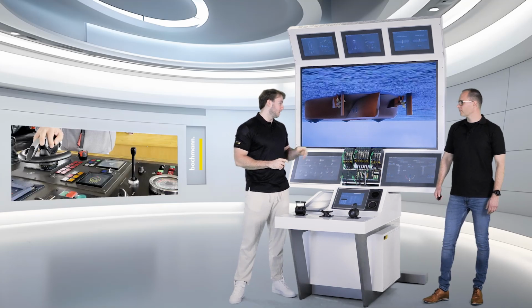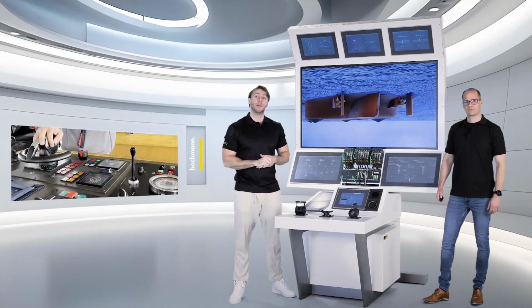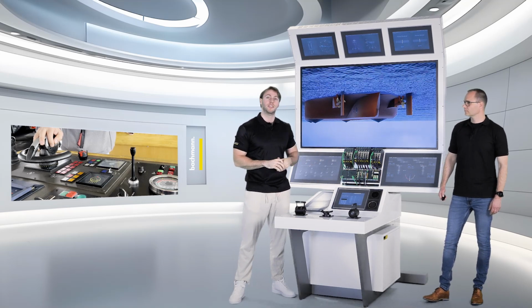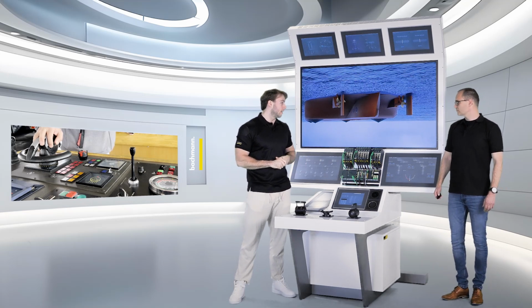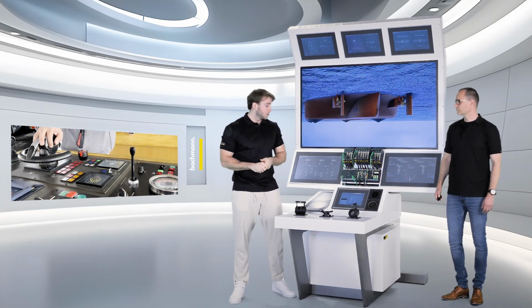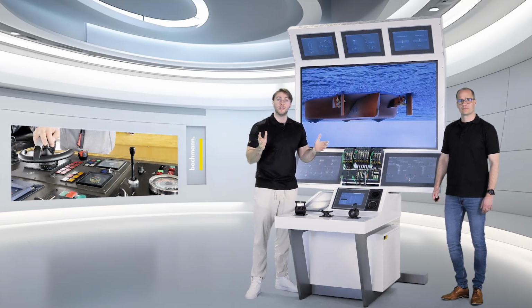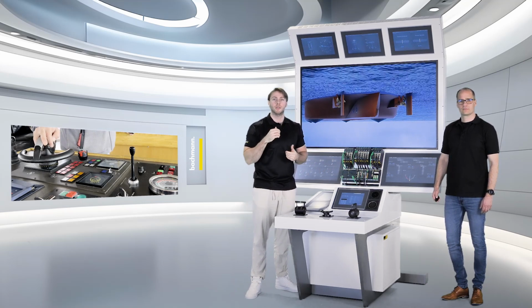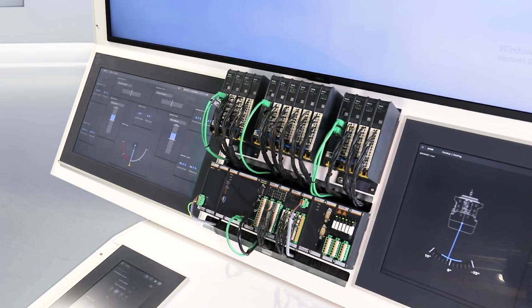So in this template we had a few objects in it, and also the brightness and the coloring of all the objects inside the project will change with a simple click of a button. Besides that, it also has some diagnostics to it. So first up, the M200 system. You have a full diagnosis on your HMI. You can click per card, per channel, and see what's wrong with it or if everything's okay. And the same goes for the M100 system.